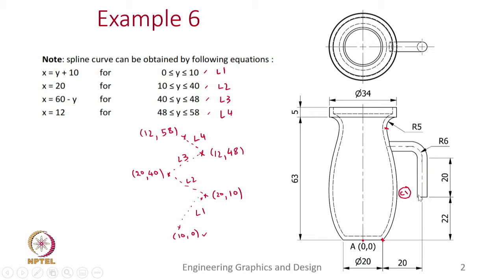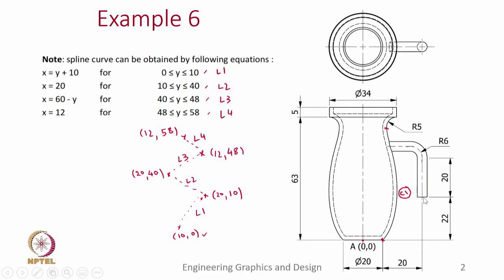Probably it is not specified on this slide, but the cross section is a circle of diameter 5. So, we will take that as a cross section and then use the sweep command, which goes initially vertical and then another curvature of r equal to 6 and then the horizontal line. So, we need to create both the profile and the path.